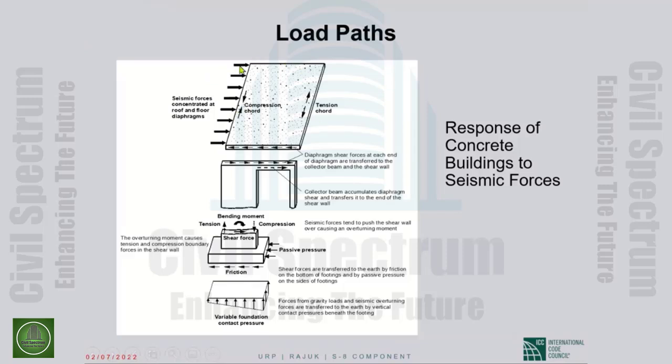This slab, when subject to those lateral forces, will act like a deep beam in its own plane. And when it does that, this is called a diaphragm. So compression will develop along this edge of the diaphragm. Tension will develop along the opposite edge, which has to be taken by what we call chord reinforcement, which we'll have to provide.